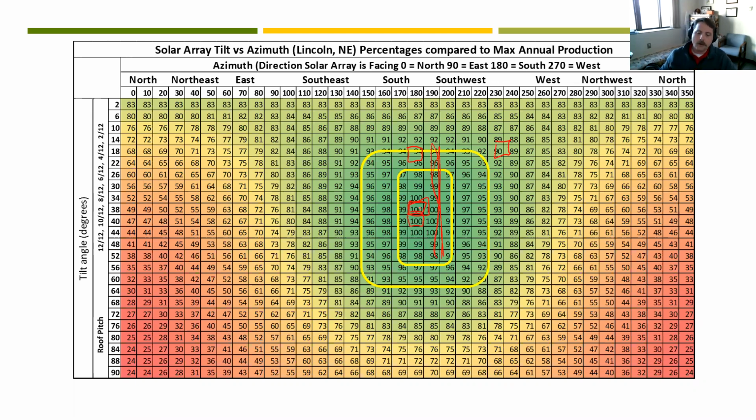So this is where the tilt and the azimuth do make a difference, but I would suggest that tilt is less sensitive than the azimuth. So you want to be closer to due south to make it optimum. And then you want to be within about 10, maybe 15 degrees of optimum. So if optimum is 40 and you're within about 15 degrees, you get within about 1 or 2% of the optimum, so it'll work out pretty well. So, just some understanding of what's going on.